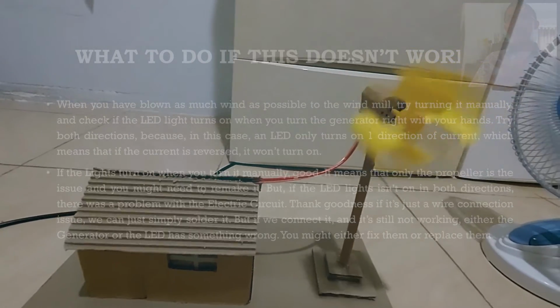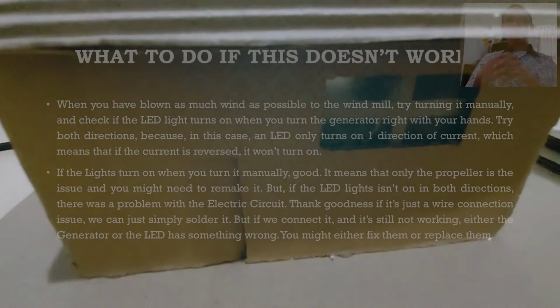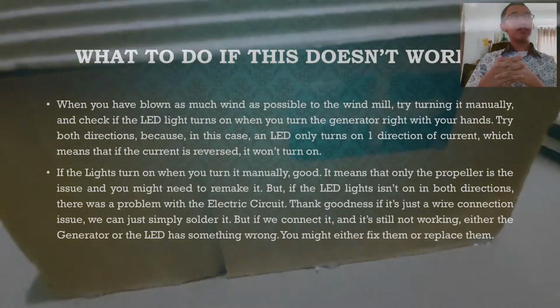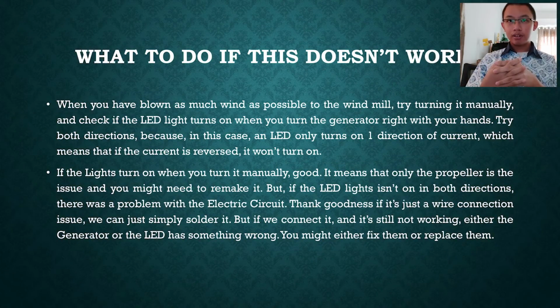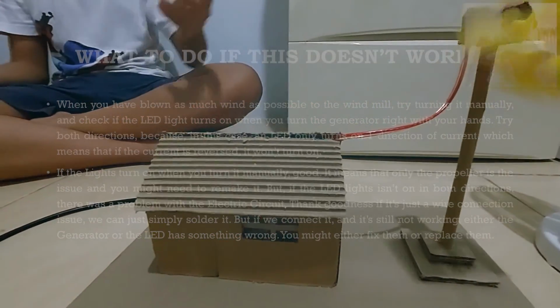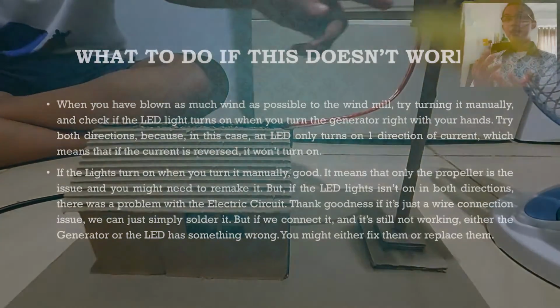But if the LED light doesn't turn on in both directions, there must be a problem in the electric circuit. Thank goodness if it's just the wire connection issue, where you solder it back together and it works. But if we connect it and it's still not working, either the generator or the LED has something wrong. You might either fix them or replace them.